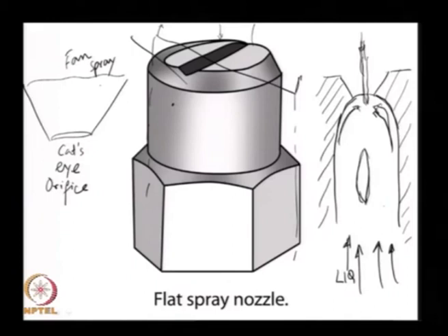Most pressure washers that use high pressure water for cleaning use a design like this. So, anywhere that you require a flat fan like spray with a reasonably low drop size. You do not want something that is completely atomized, because the intention of these applications is to actually have drops impacting the substrate and cleaning dirt or grime. I do not want to create a mist that just diffuses into the air.